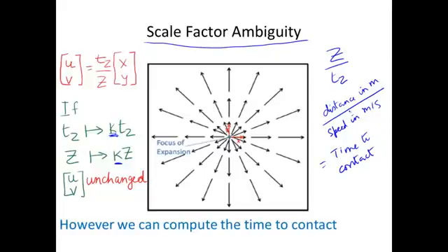In fact, this advice seems to be followed by insects and birds and so on and so forth. There have been quite a few experiments done by biologists which demonstrate that time to contact is a very valuable variable which is in fact used. So you can control essentially braking behavior by making tau decrease as appropriate. I'm not going to get into the details of those studies, but the beautiful result is that from the optical flow field we can determine time to contact, which is in fact the variable we want to use for controlling our braking behavior so as to avoid colliding with obstacles.